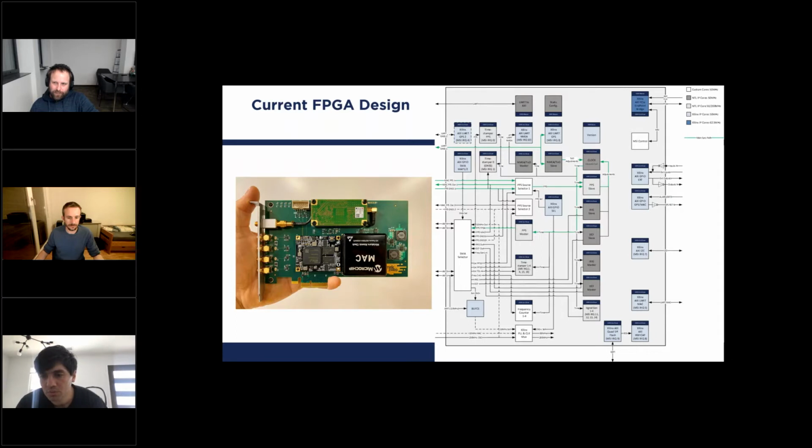Just to add to what Sutton was asking, an M.2 is very restrictive in terms of real estate, and you need to have the GNSS receiver and a MAC. So we've been looking into high stability oscillators, smaller OCXOs, or TCXOs. And for the GNSS receiver, either miniaturized versions, or some alternatives. Let's say use a UWB receiver, where somewhere else a GPS receiver sends you the PPS over UWB. So we've been exploring different options, if that answers your question.